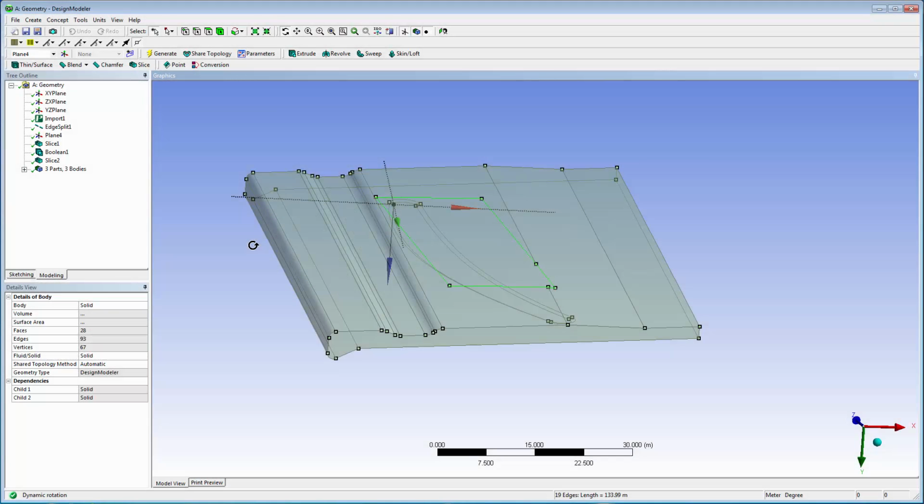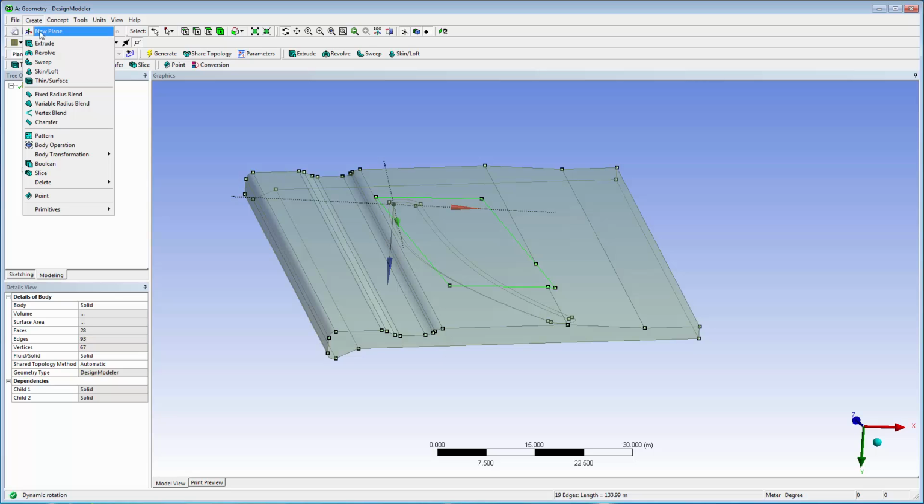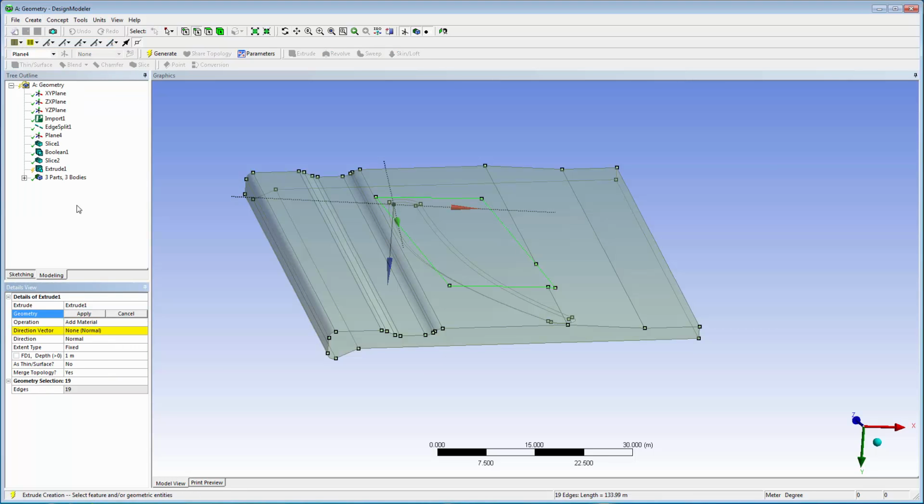If I extrude these edges through the plate, I can slice out the key part of the intersection region, which will help later when I want to get an all-mapped hex mesh in this region. It's important because the intersection region shares interfaces with the blade, plate, and hub, and these faces need to be map meshed to sweep the neighboring bodies.